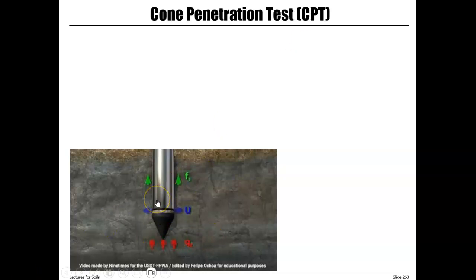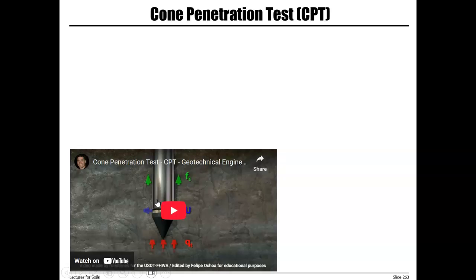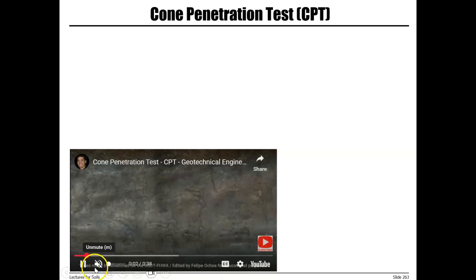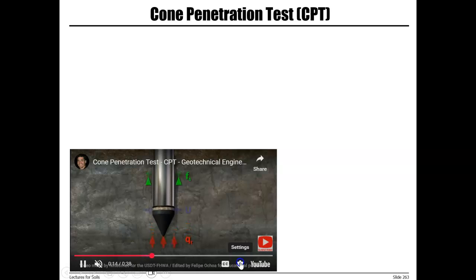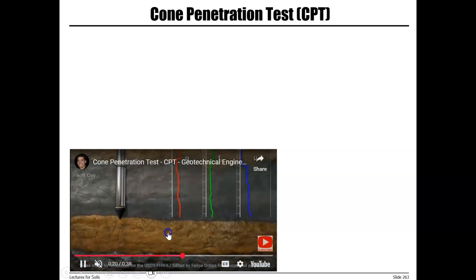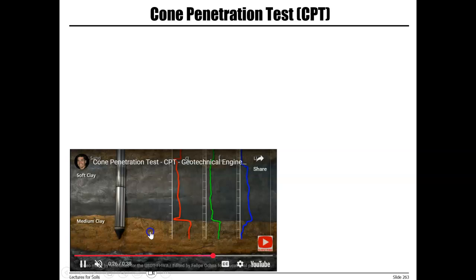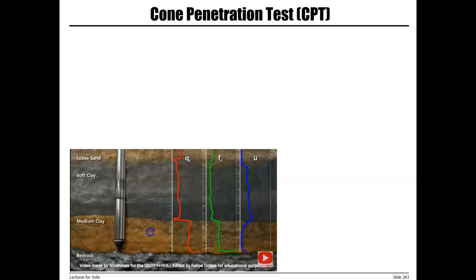So it's again a simple test. It's a fast test. It's continuous. It doesn't cause disturbance to the soil. A rod is pushed into the soil, and at the same time, the resistance, the frictional resistance, and tip resistance are measured.